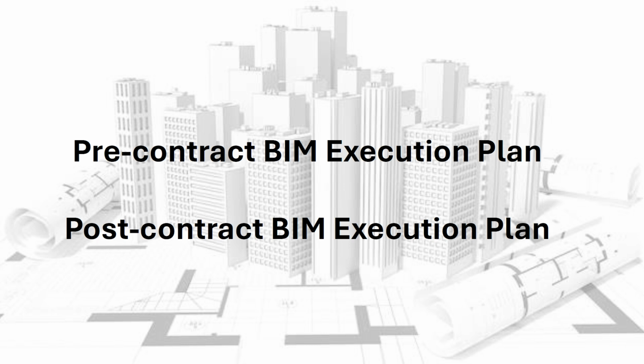1. Pre-contract BEP. This type of BEP is prepared during the tendering or procurement phase, typically by the client or project owner. It outlines the client's BIM requirements, expectations, and standards for the project. 2. Post-contract BEP. This type of BEP is prepared after the contract has been awarded, typically by the contractor or supplier. It outlines the detailed plan for implementing BIM on the project, including the scope, responsibilities, and procedures.